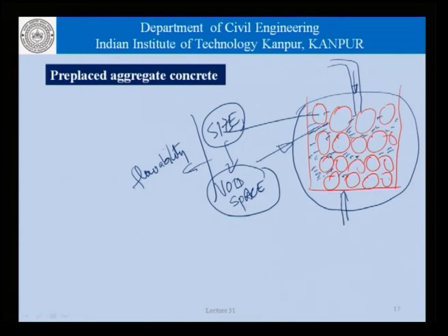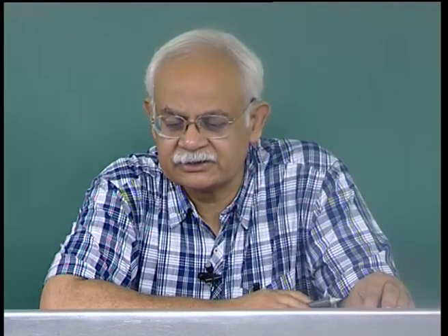If we are pushing the grout from the top, there is a possibility that the grout might not reach all the spaces, whereas if we are pushing it from the bottom, the chances are that we would be able to accomplish a higher filling, even though it is more difficult to do. So, there are issues related to pre-placed aggregate concrete, but in this limited discussion that we have, I am just trying to show it as an illustrative example related to grouting. As far as the subject is concerned, there is a lot more to study than of course this.